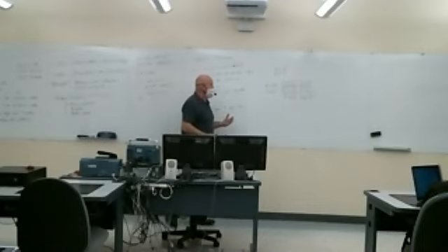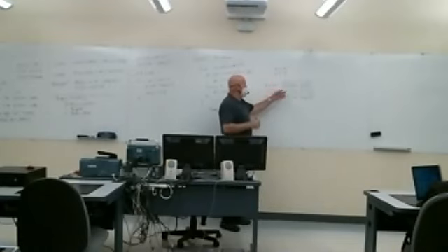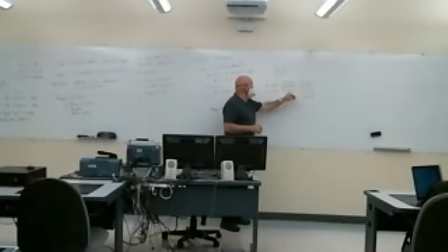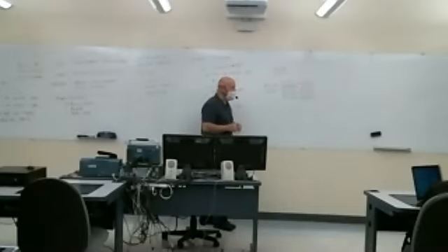I could check to see if B5 is 0 or not. I would AND it with 0x20 to check B5. Or I could check to see if both B5 and B2 were 0 by ANDing with 0x24. In that case, there are 4 possibilities though. They could both be 0, in which case I'd get 0, or they could both be 1, or one could be 1 and the other 0. There'd be 4 possible outcomes there.